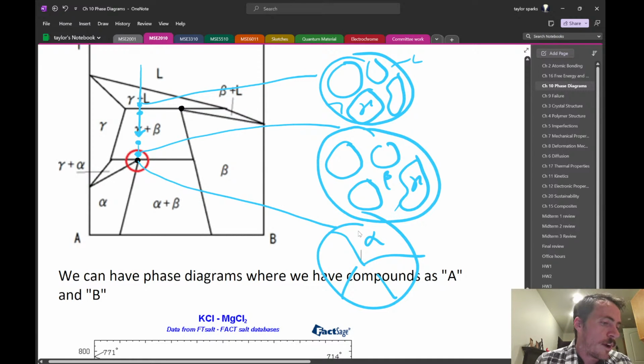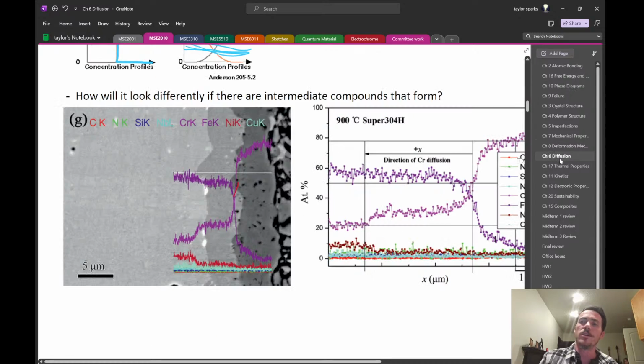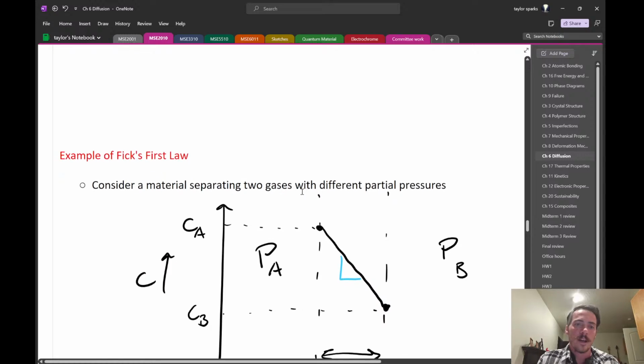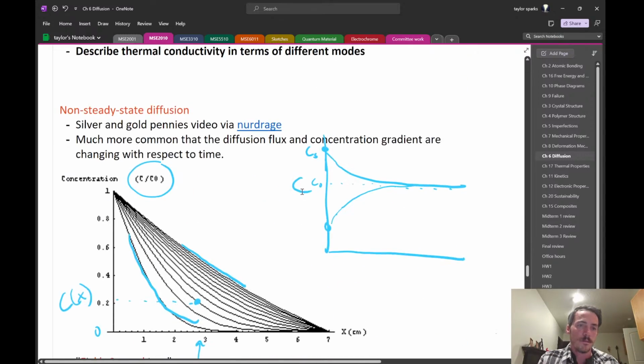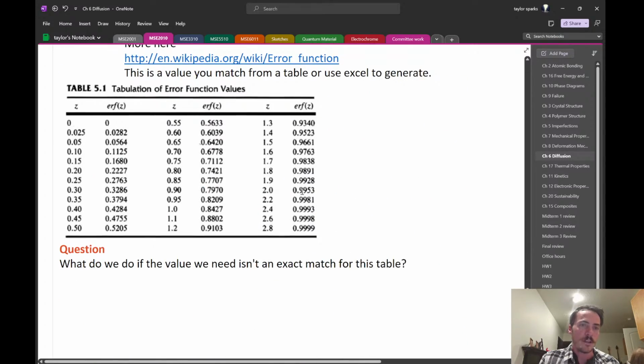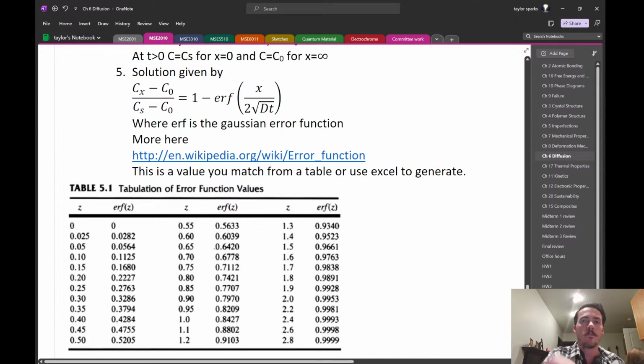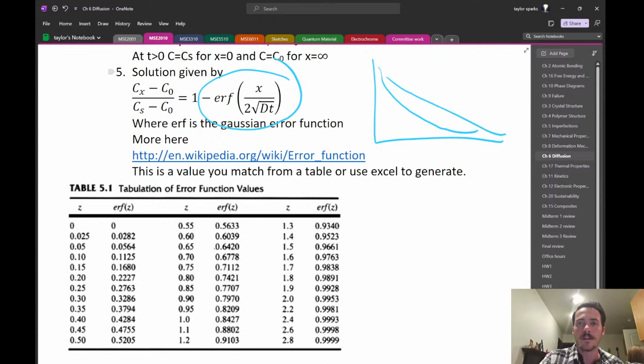Can you review error function tables? Yeah, we can do that. Error functions we introduced in chapter 6 with diffusion. If we scroll down to this, we learned about them right here. So the error function tables we use simply because that's the mathematical thing that allows us to basically get this S-shaped curve, right? When you do these diffusion profiles, it's these sort of bent curves. The error function is a pretty convenient way to achieve that shape.